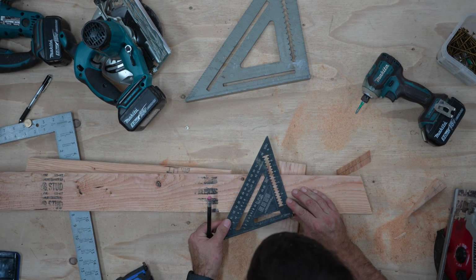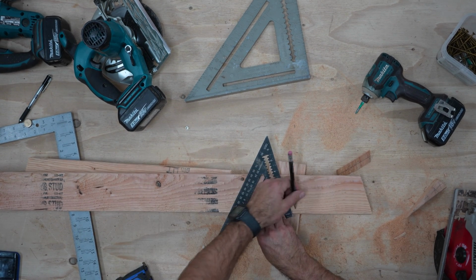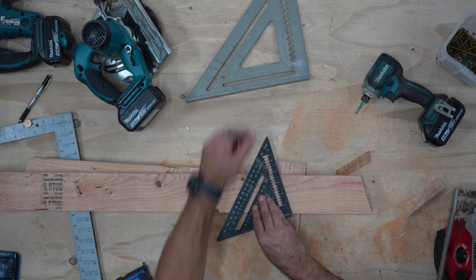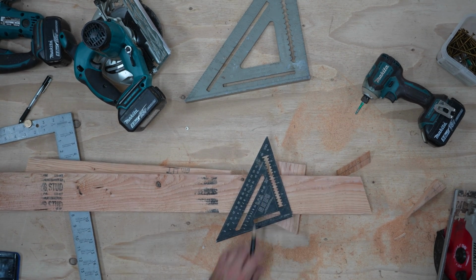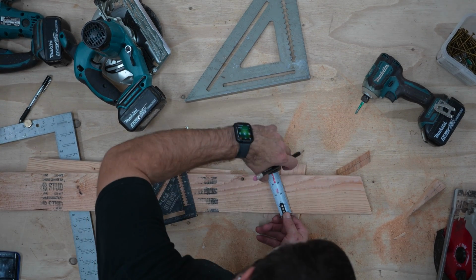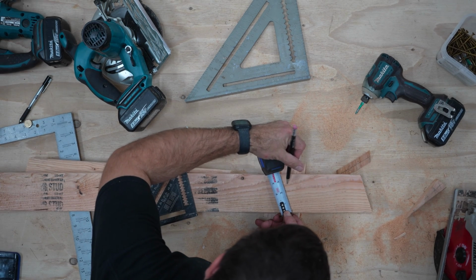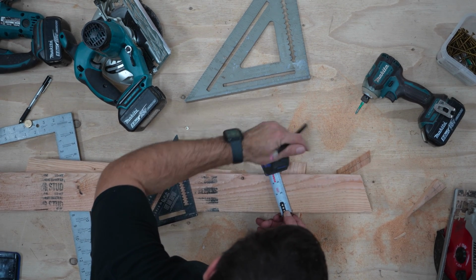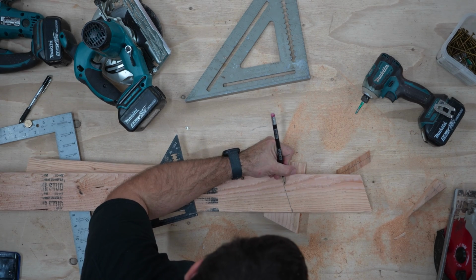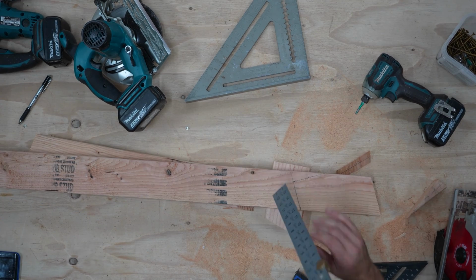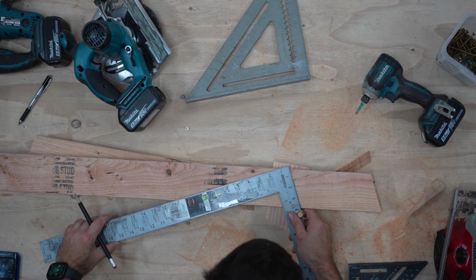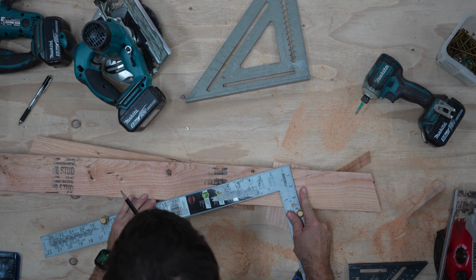All my plumb cuts for the jack rafters are back to the 4-12 plumb cuts. The only rafters that get cut at 14-17 plumb cuts are the hip rafters and the valley rafters. All the other rafters, even if they join to the hip or valley rafters, will be cut at 4-12. This is why, if you notice, I'm not using the stair gauges against the board to mark my lines.